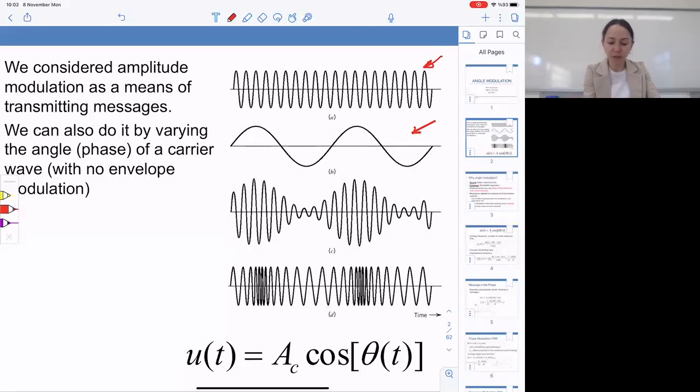In C, you see something that you recognize as double sideband suppressed carrier amplitude modulation, because the information on the message signal in B has been embedded into the amplitude of the carrier wave. In figure D, you see something different. What's going on in this figure?